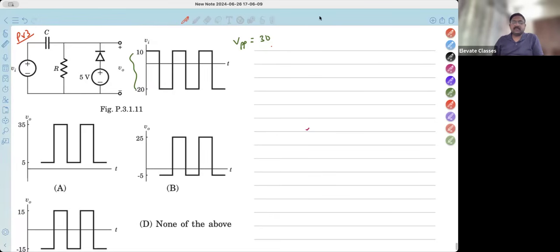One simple thing you can do is this. This is your node. What do we call a node? Where the capacitor, resistor, and diode are connected. Again, check which terminal is connected, P and N. For clippers, if N was connected, we called it a negative clipper. For a clamper, what do we do? We go exactly opposite, right? We go to the exactly opposite thing. So since N is connected, this is a positive clamper.